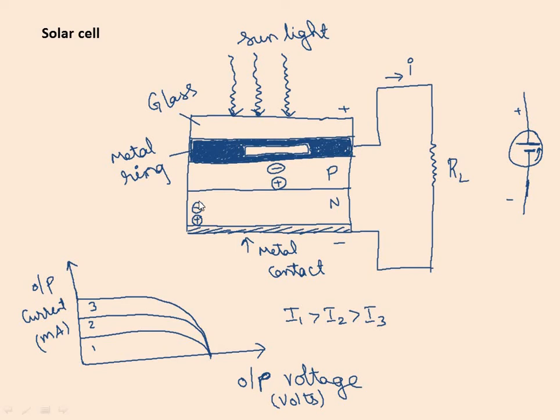You can see here it has a PN junction diode. It is made of either silicon, pure intrinsic, or extrinsic gallium arsenide, GaAs, either intrinsic or extrinsic, and a thin layer of p type is grown by the diffusion of a suitable acceptor impurity on an n type semiconductor.